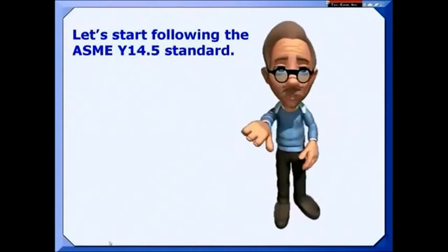On nearly all of your parts, you need to establish origins of measurement. We do that by selecting datum features that are used to establish datums. Because these datum features are features, they need to be controlled, so we put tolerances on those features, and that's really been clarified in the 2009 revision of the standard.